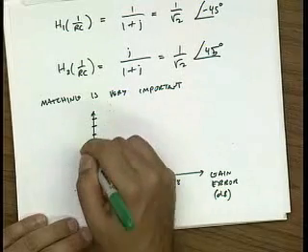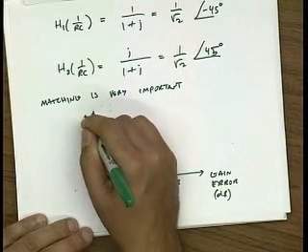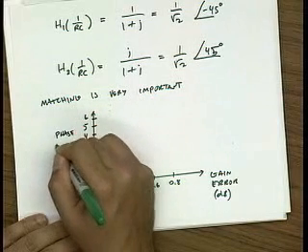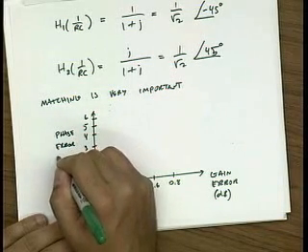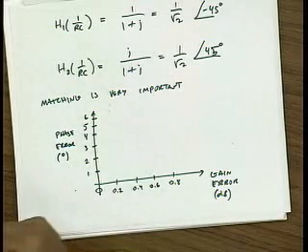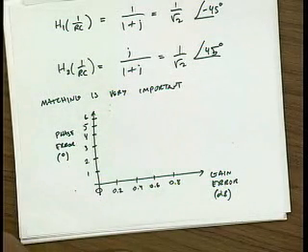On the y-axis, I'm going to plot the phase error, 1 degree, 2 degrees, 3 degrees, 4, 5, up to 6 degrees. So this is the phase error in degrees. And what you can do is plot contours of basically constant image rejection.